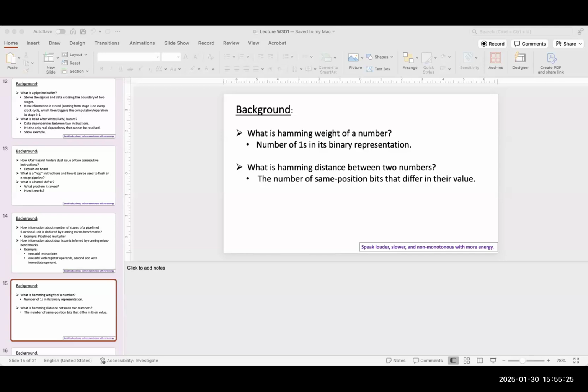After their investigation, after doing the CPI analysis for different kinds of micro benchmarks and looking at the results, they constructed a figure describing what they think about the internal details of the ARM Cortex processor. They found that in the register file you have 3 output ports, you have 2 output ports. They found that you have multiple ALUs, one of them has a single stage, the other has 3 stages, and the load store unit and FPU are also pipelined.